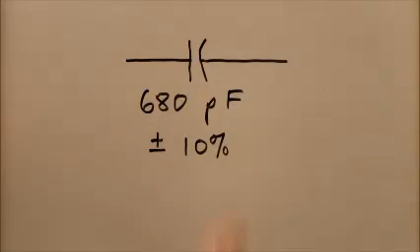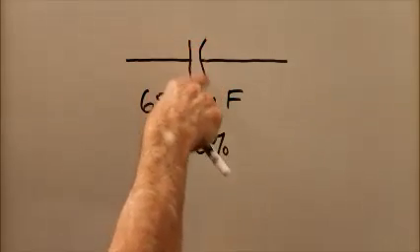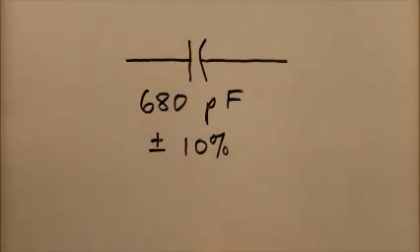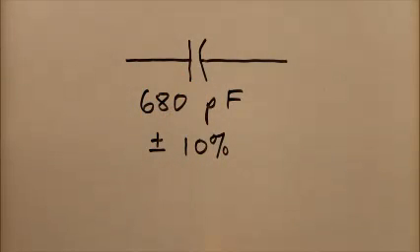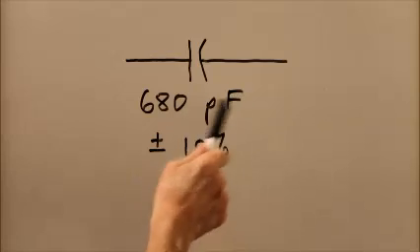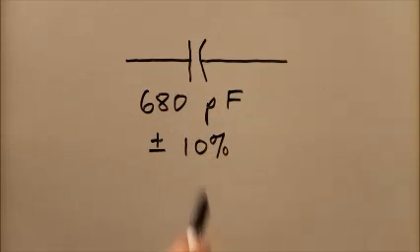Here is the symbol for a capacitor. Remember that curved line that you will often see, not always, but often, in a capacitor symbol. The curved line usually represents the side that is more nearly connected to electrical or chassis ground. That's just a convention that you will sometimes see. Just as a little aside, but this is the situation.